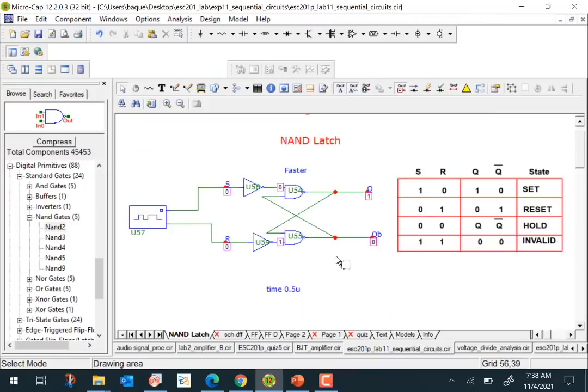So in addition to the gates having different delays and that determining whether the output goes to 1 or 0, a similar thing would happen depending on which input arrives faster. For example, if this one arrives faster as compared to this particular input, then you will get one particular kind of behavior at the output. On the other hand, if the other input arrives faster than this one, then you'll get a different kind of output.